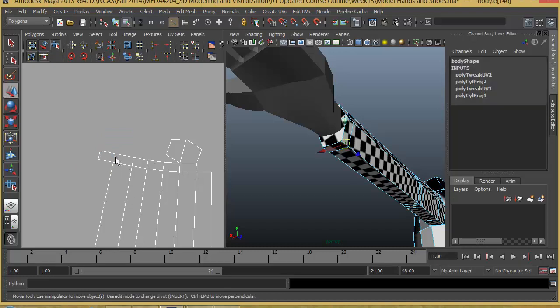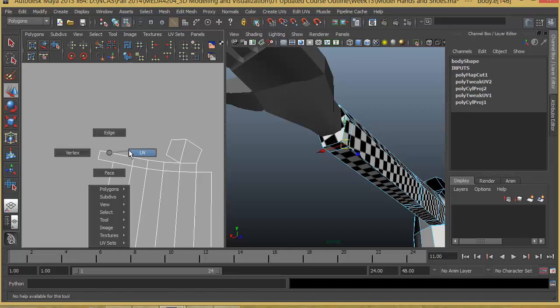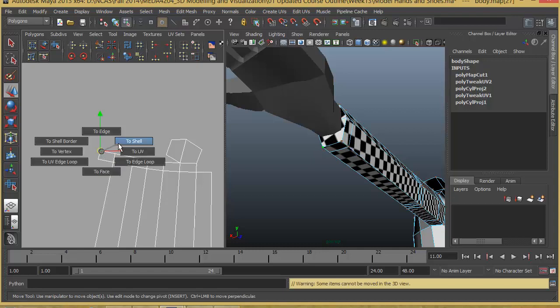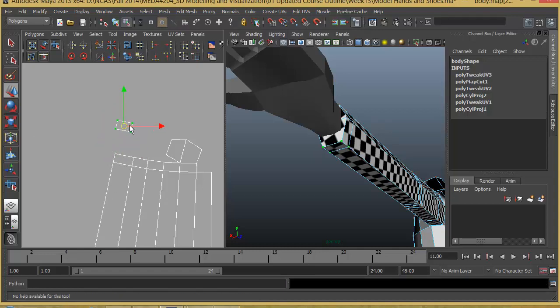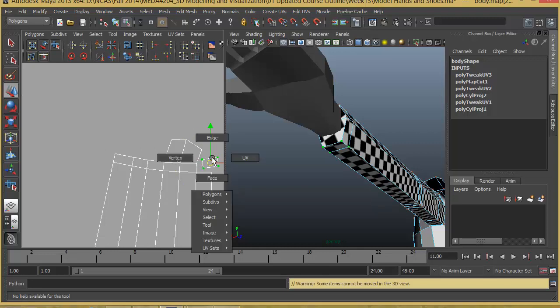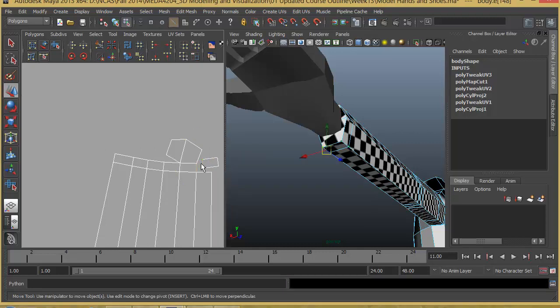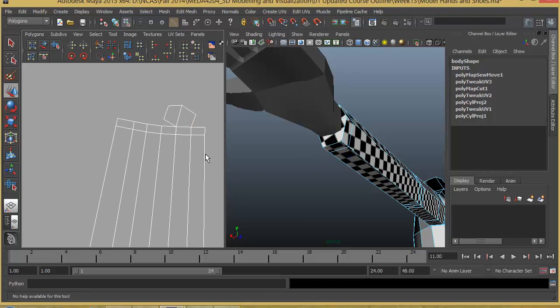Let's click here, so that edge is being selected. Now I can cut this UV so that these UVs would come out. I'll select this UV and control right click to shell, so you can see that it comes out, and I can push this to this other side and connect them. So I'll just rotate it a bit. Okay, now we can also select these edges, and it would actually show us where this edge will go and where this edge will go. So I'll select these two edges and choose this button that's for move and sew UVs, so that they will be connected properly.